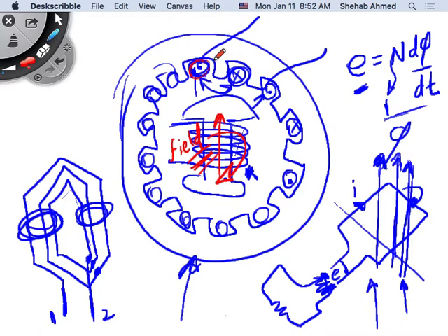And it will link these coils differently at every instant of time, and hence generate a time-varying magnetic field, and hence generate a voltage across the terminals of the winding. If this variation is sinusoidal, for example, then I can generate a voltage that's also sinusoidal. Correct? So I can create a sinusoidal voltage across my windings. This is a simple explanation of how a synchronous machine works without getting into details, because we don't care too much about the details in this course, right?